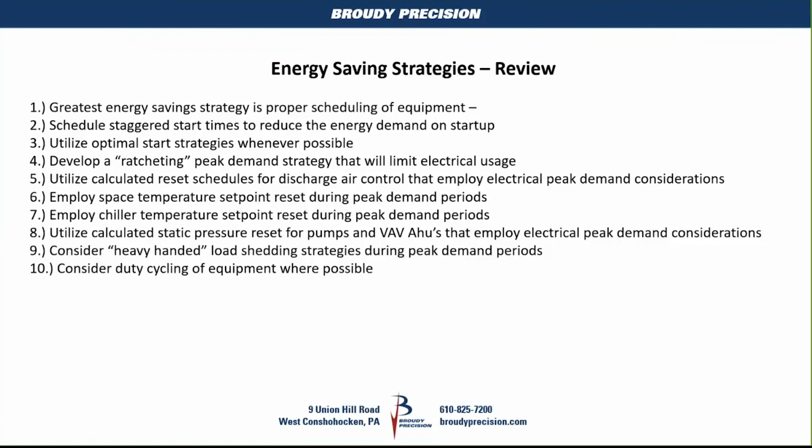So one of the things that I always use when I write software is the calculated reset schedules for discharge air. So you use space temperature and you use discharge temperature of the air handler. This works particularly well with modulating service, not so much with heating or cooling.